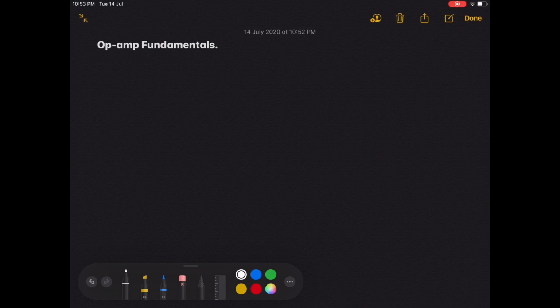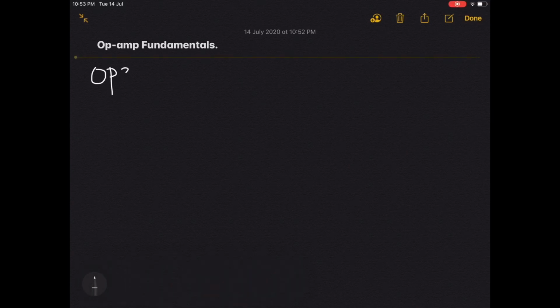So, what is op-amp? Op-amp is a direct coupled high gain amplifier, usually consisting of one or more differential amplifiers, usually followed by the level translators and then the output stage. So, in an operational amplifier we have differential amplifiers. It is the combination of differential amplifiers, followed by the voltage follower, and then the complete circuit acts like an operational amplifier.